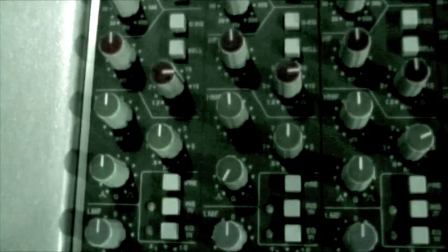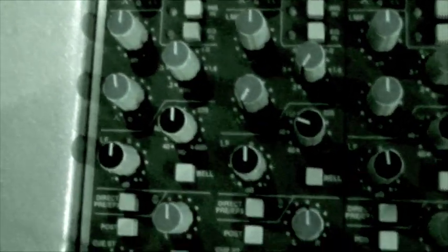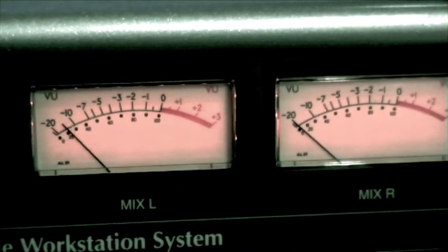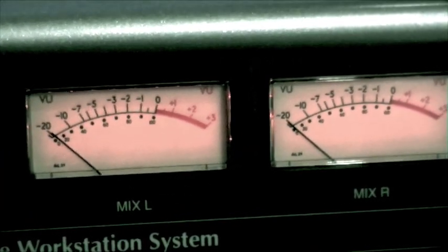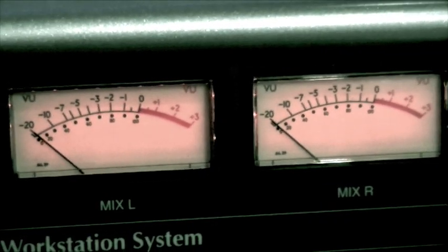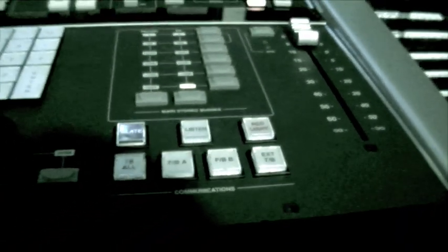For example, many experienced audio engineers know that if the EQ section of a console is not bypassed during recording, it can have an apparent effect on our recordings, even if the gain dials are set to 0. This is due to the filter structure and analog nature of the console. This is also due to the signal passing through the electronic circuit that implements the EQ.